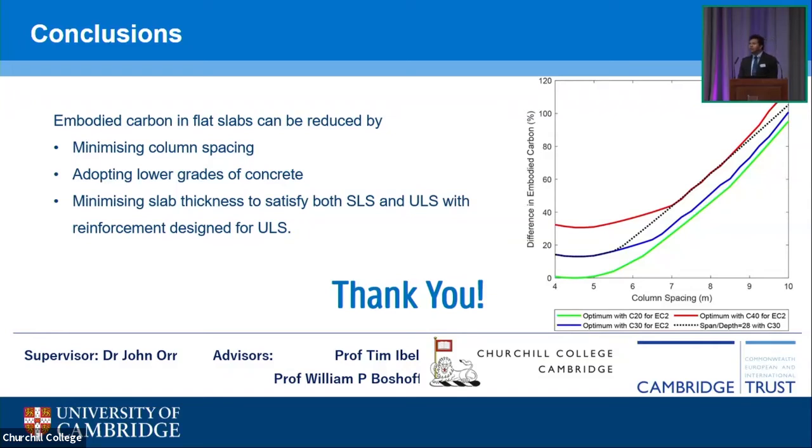Well, I guess you are talking about the finite element analysis, not the overall approach, right? Yeah, how much do we trust the results of the finite element analysis? I think it would depend on the case. They say no matter what kind of sophisticated model we use for finite element analysis, the results would vary within, I think, plus 15% to minus 30%.